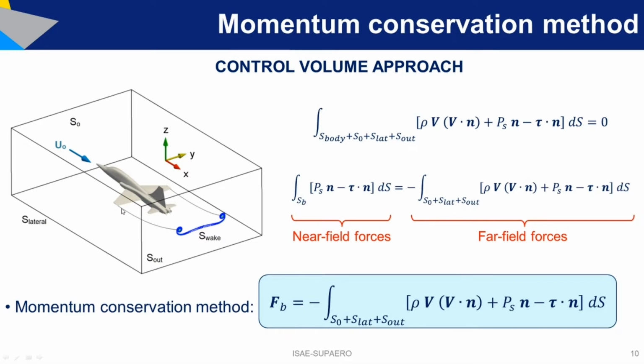This, in any case, is a smaller drawback, but it becomes absolutely prohibitive for wind tunnel testing, and this is more evident. Why? Because in a wind tunnel testing, you cannot afford to measure all these parameters on all the surface. That will require a lot of wind tunnel testing time, and simply you cannot do that.